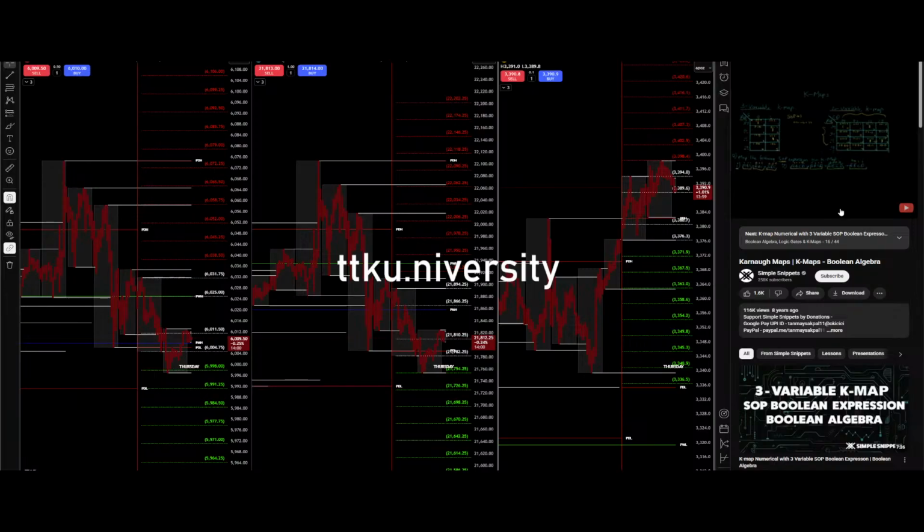Now notice that both these equations are standard SOPs. That is, every product term has all the 3 variables ABC, ABC, ABC. And for the 4 variable, we have ABCD, ABCD, ABCD and ABCD. So whenever we map a Boolean expression to a K-map format, we first need to convert it into a standard POS or SOP format. So just keep that in mind. When we actually solve these problems, we'll have to do that calculation as well. So this was just for the mapping. I'll discuss grouping, adjacency and simplification in the next tutorial.